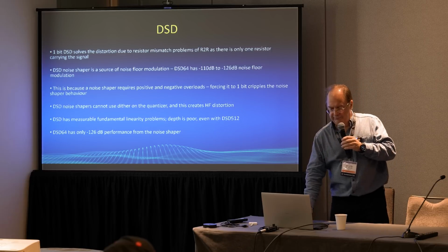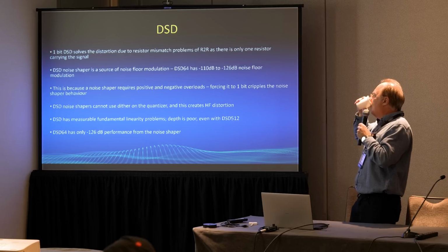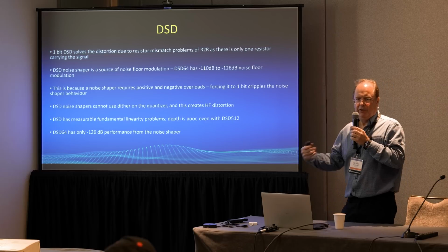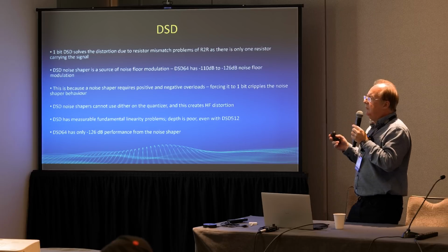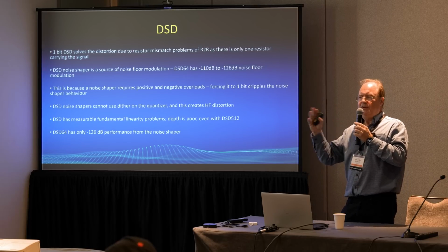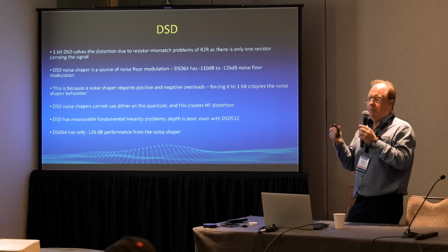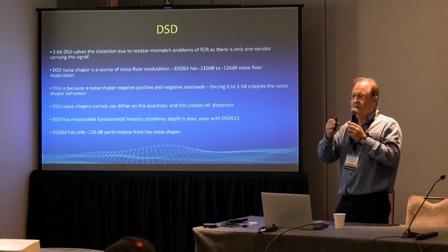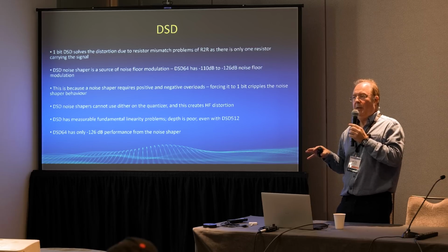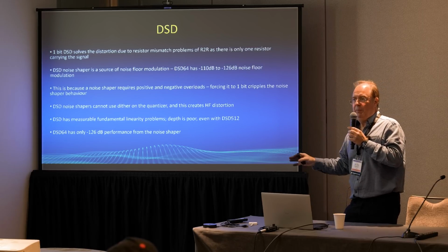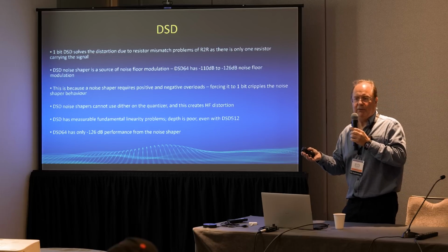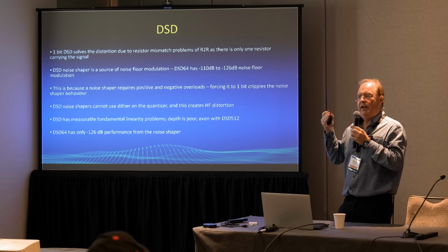So, DSD. Now, I talked earlier about R2R DACs having problems with mismatch, and that creates lots of high frequency distortion. The beauty of DSD is that it solves that problem because there's only one element, so there's nothing to mismatch. And indeed, when you look at DSD, if you do a distortion plot, you'll find that distortion at minus 60 dB starts to completely disappear. And as the signal gets smaller, the distortion disappears. That is the same way that the ear behaves. So it's completely the opposite to R2R DACs, where as the signal level gets smaller, your distortion level gets larger.